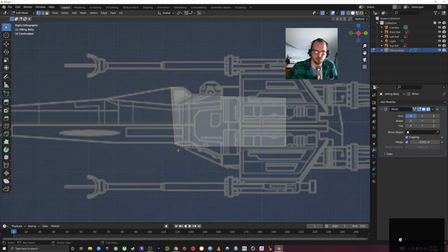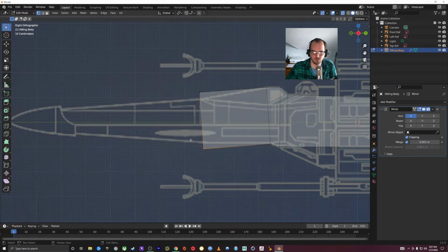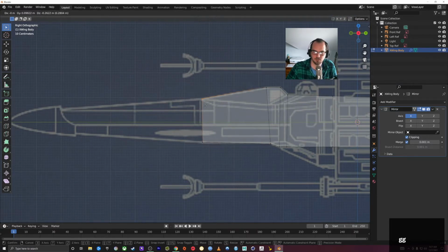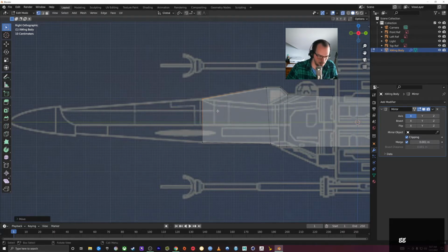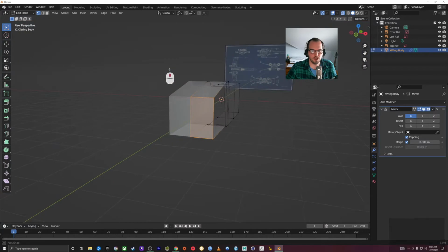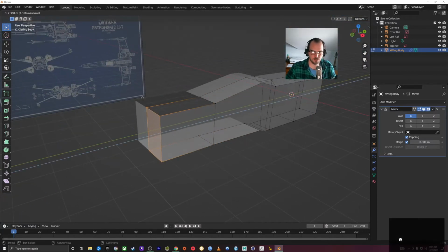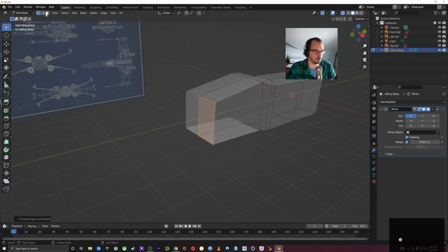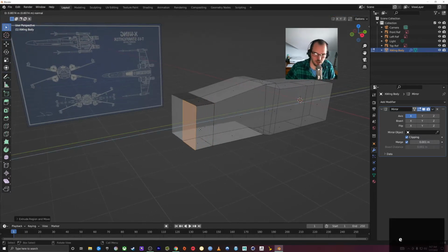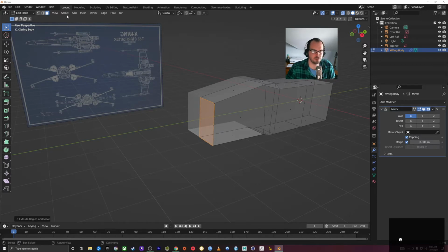I'm going to select all these front ones again. Extrude here. And just kind of try to line these bottom ones up, line these top ones up here. Extrude, whoops, grab all the front ones again. So when you have 4 points selected and you hit E to extrude, it's going to extrude the whole thing. I could also be working with face select. I could come over here and do E extrude again, but it's essentially doing the same thing.